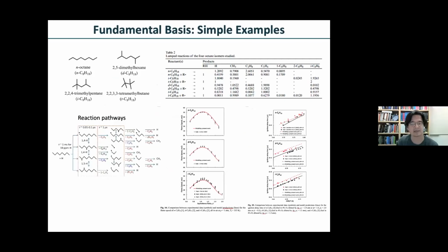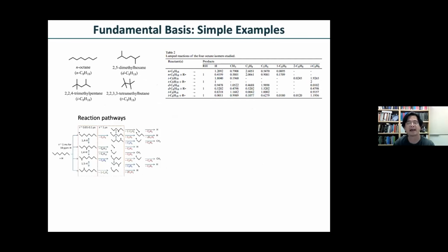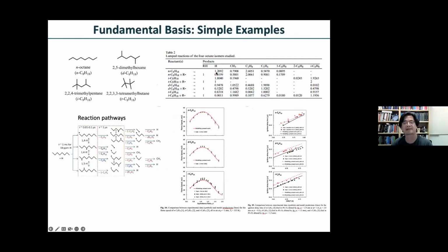For those who are interested in this problem, you can read some of those papers, which I'll give you the list of at the end. The key point is, by throwing away perhaps thousands of reactions, just to write it simply, I have, for example, the fuel dissociated into hydrogen, methyl, ethylene, and so on. Each of these values is related to alpha, beta, gamma, the Greeks, that I showed you earlier. Then you have a second reaction, with a series of radicals and their stoichiometric coefficients simply derived from the detailed model.